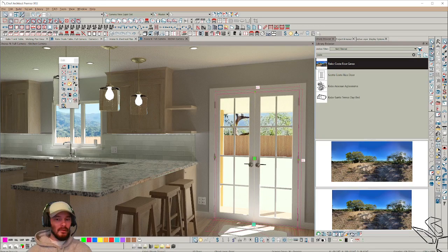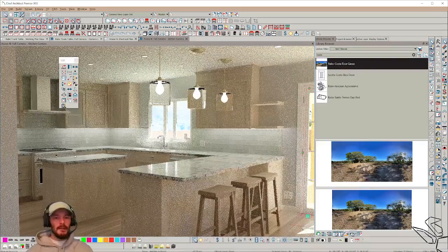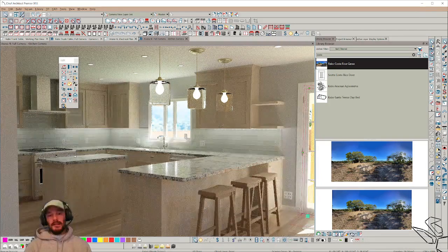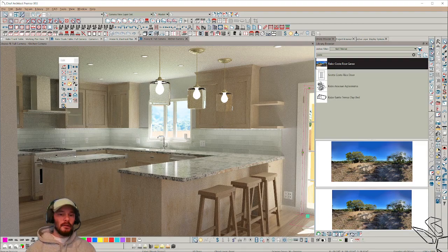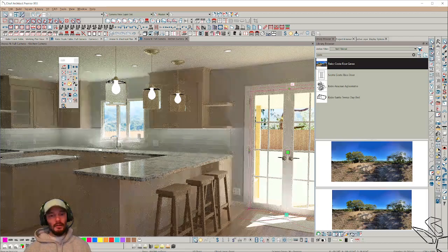You don't need to change the sun's intensity. You can keep the sun's intensity just the way it was. Just change the direction, because by default, the sun is facing the backdrop, which is then illuminating the backdrop. That's something that I hope they fix, but this is an issue I see a lot of. So if you guys are wondering how I'm getting better results out of my lights, one is creating light sets, where I'm just ensuring that lights are turned on in a scene. Two is that I'm ensuring that my sun is not facing my backdrop unless I really need it to, right? And then I'm adjusting my backdrop intensity based on that.